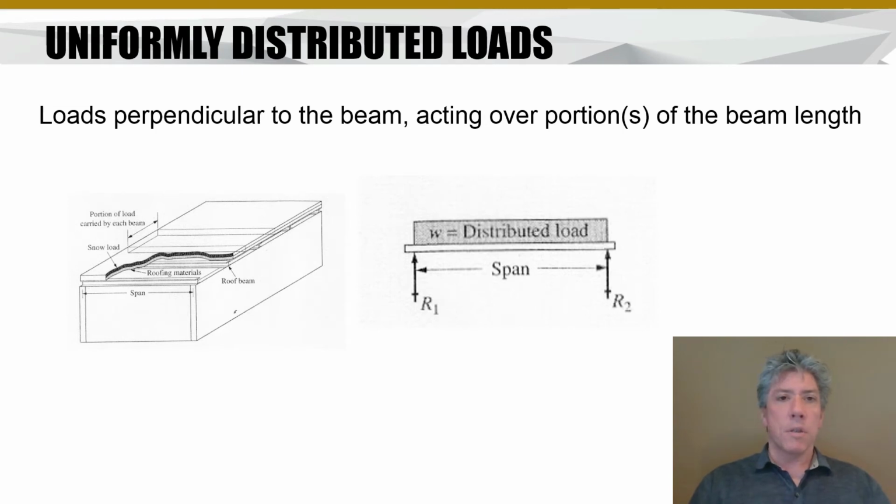Well, I had to consider two parts to that load, that transverse load on the beam. One part was people walking across it, right? Or my piano, for example, that I put in there. And the other part was the dead load. And the dead load was just the uniform load from the layers of plywood I had to put down, the ceramic tile, and the underlayment under the tile that was required. And so that all is dead load.